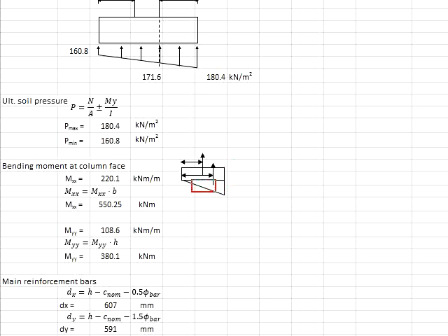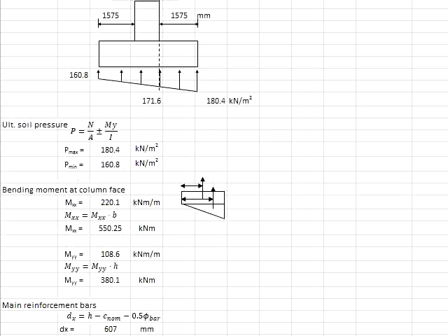And then find the resultant force of this triangular stress, which is located at 2/3 from the face of the columns. The resultant force to be multiplied with the lever arm here will give you another moment. The summations of moments for both will be equivalent to your moment acting on the surface of the columns.